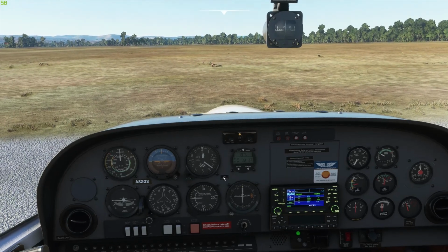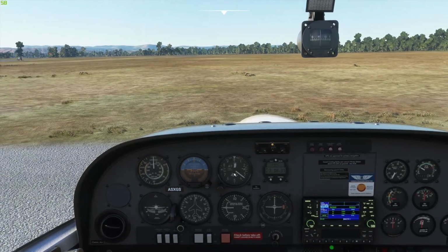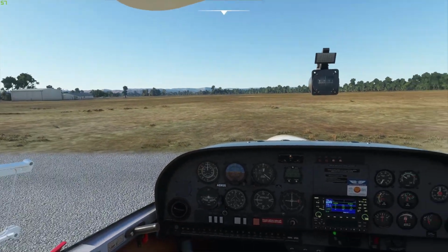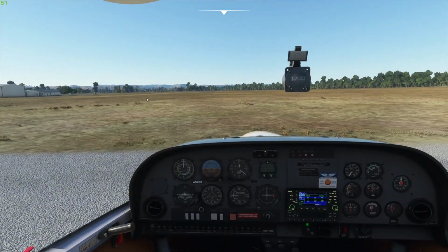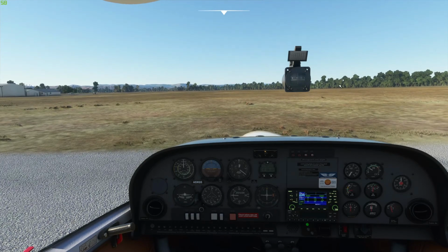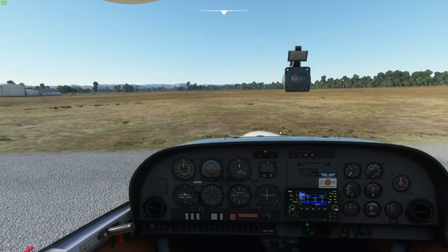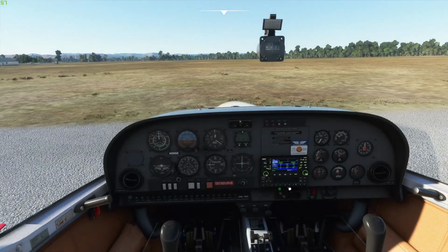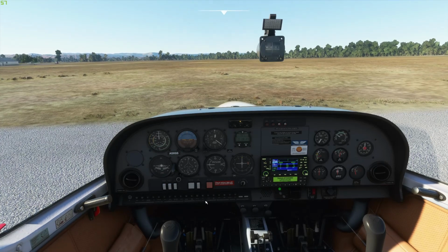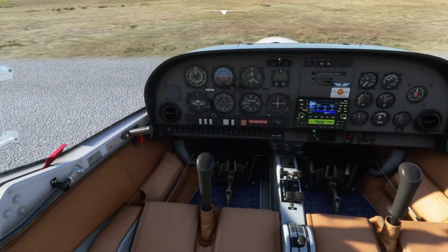Okay, QNH is set, so on the ground we're at 340 feet. We're at Masterton here, where we've operated last time. So we taxi out on the grass here to the seal, and we'll just take off on runway 24 to the south. And we'll climb up to 3,000 feet to the east of the airfield in this area. Nice clear day for our handling exercise. So that's about it. Transponder we can put into standby, let that boot up. Masterton set in the GPS conveniently, that's nice.